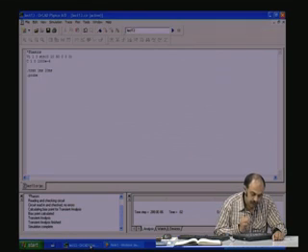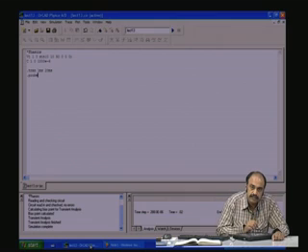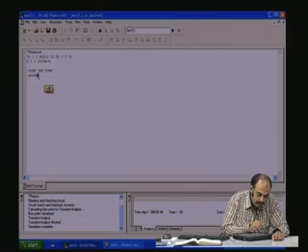So, going to this PSpice editor, we have here Vi, V input, between node 1 and 0, a sine wave source, 0 DC offset, 10 volts amplitude, 50 hertz, 0 rise time, 0 fall time, and no phase shift.